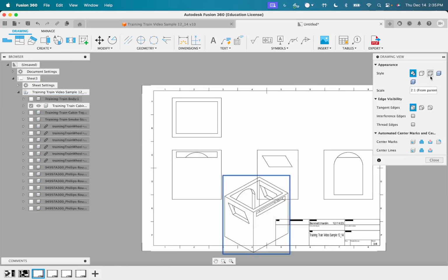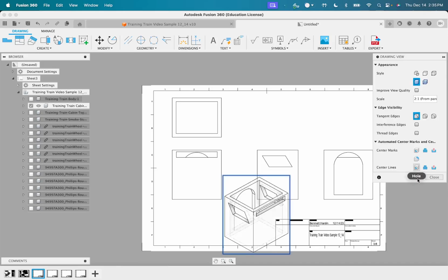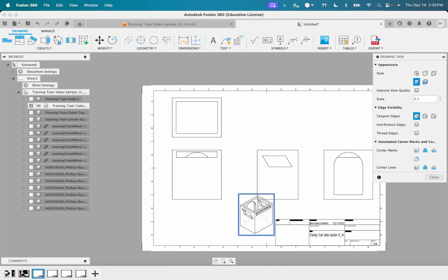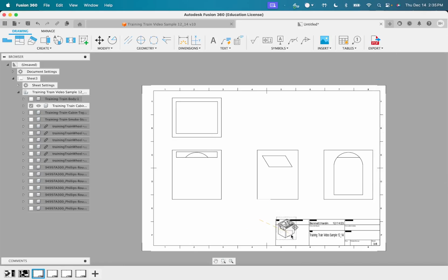We'll go ahead and give this one shaded, and we'll descale it to, let's do 1:2. So we'll fit in our box, and we can drag it down here. So there we go. And now we can start to give some of this stuff dimensions, very similar to what we were doing before. Sizing.